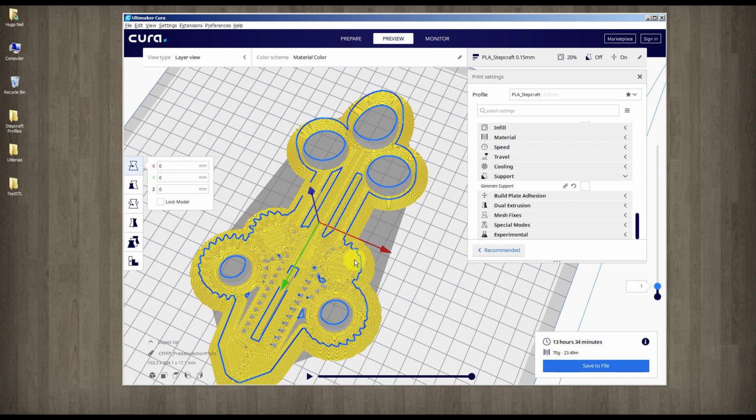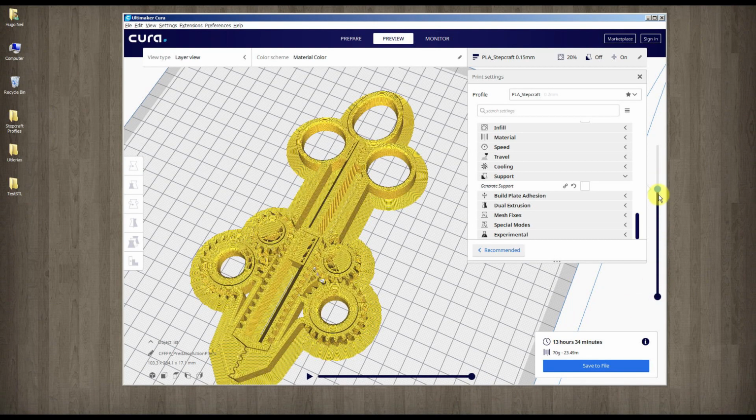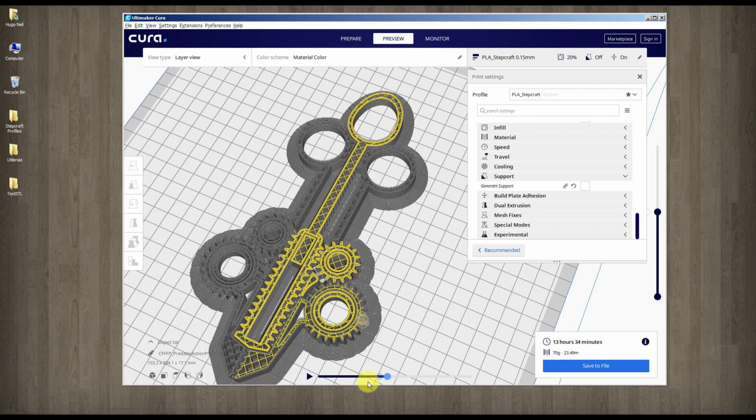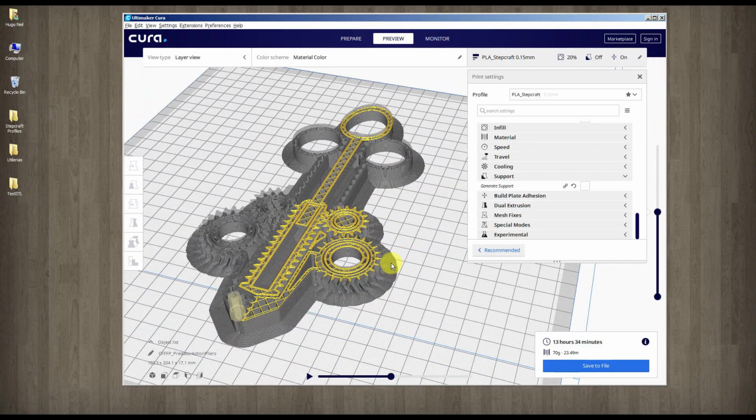But if you have a heated bed, maybe you don't need the brim, so the material is going to have a good support. Because in my case, I have to put the brim so I can have a good support for the printing. Okay, well, basically that's it. This is the way the settings are done for a more complex object. And now I'm going to show you how this is printed.